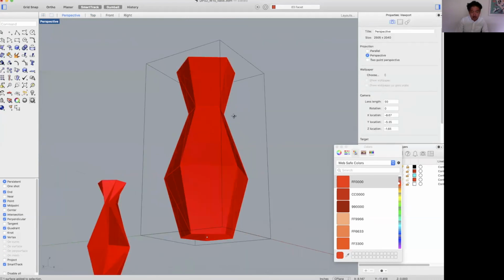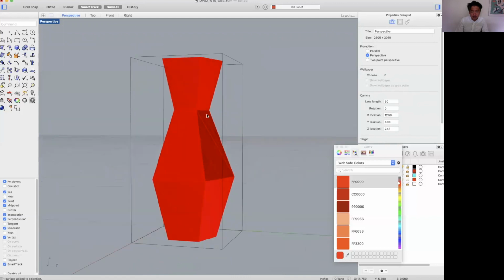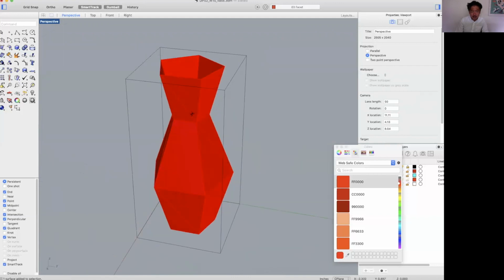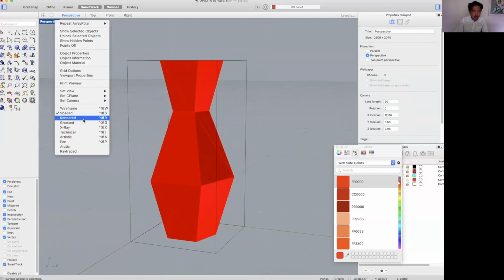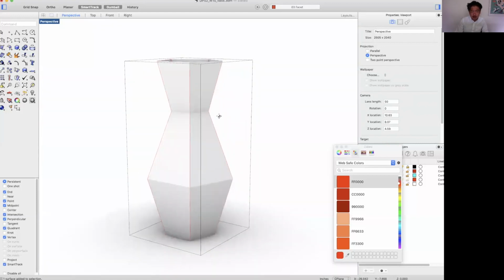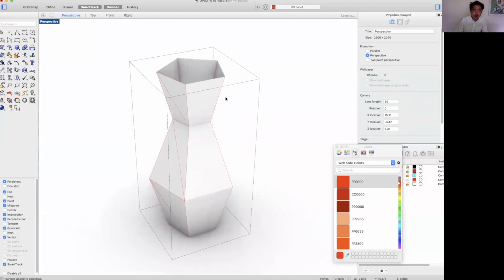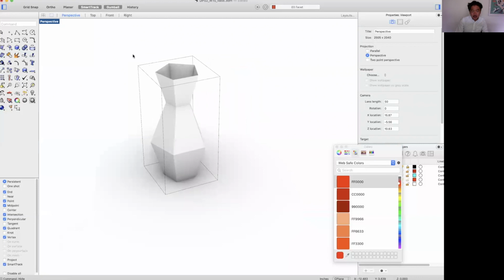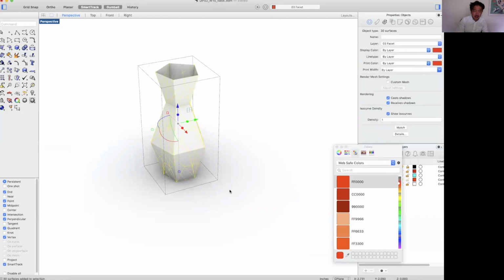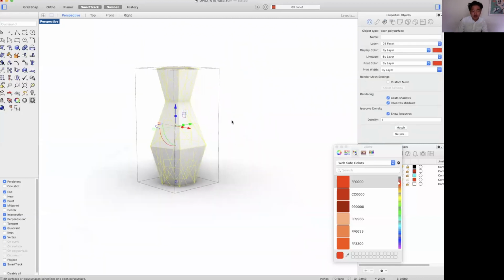But at this point, they don't have movement, so the surface is looking pretty flat. So what we're going to do is turn off all of the curves by select curve, SelCrv, and hide. Okay, and then we can actually join all of the faces.